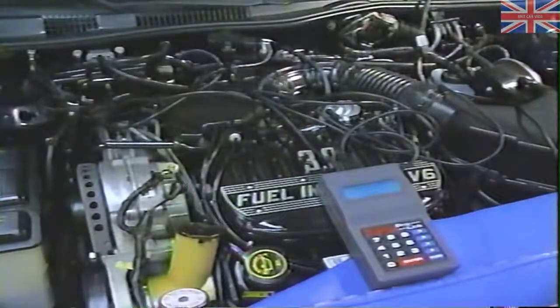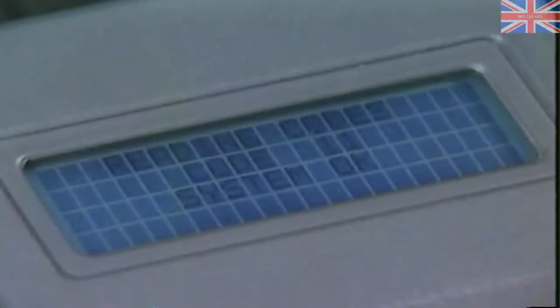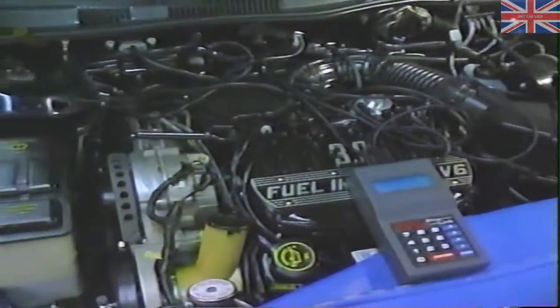Next, you will receive engine running diagnostic codes or hard faults if there's a problem detected during the engine running self-test. We are receiving a code 11, indicating that the vehicle has passed and that there are no codes held in memory. The next test we must perform is called a continuous self-test. This is where we will locate the intermittent problem.